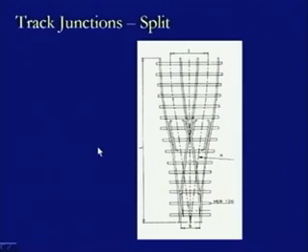This is another diagram of a similar sort of split where the jack rails, wing rails and V's etc. are all being shown properly with the thickness diagram. That is, this is one track, the thickness of the rail has been shown, and the sleepers are also shown in this one, where the sleepers are moving like this across. As we have seen in the case of the turnout, we provide the through sleepers, that is a better option than the interlaced sleepers.